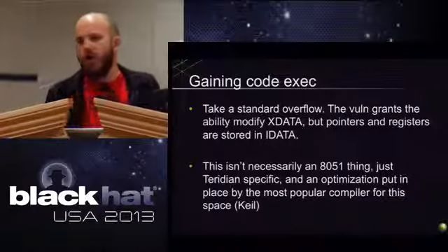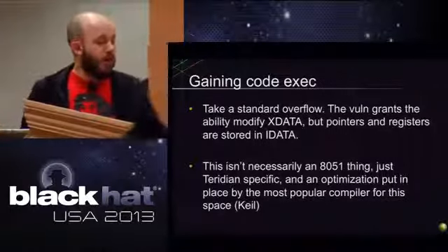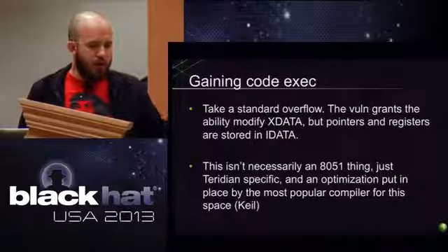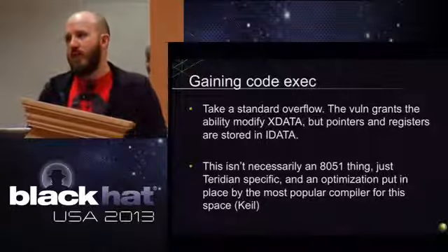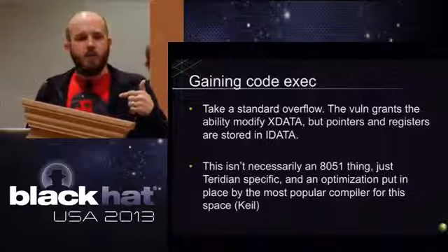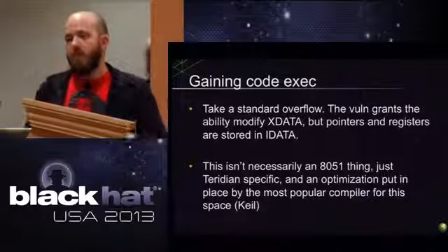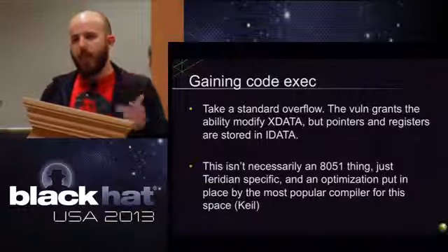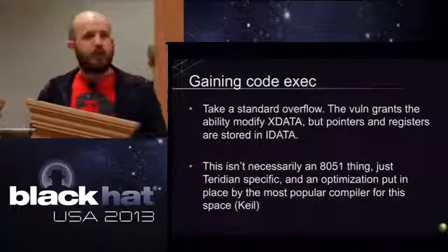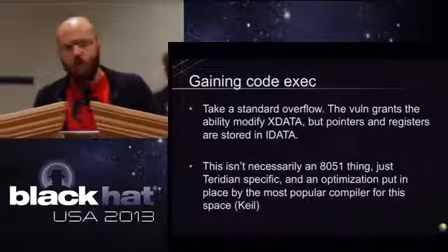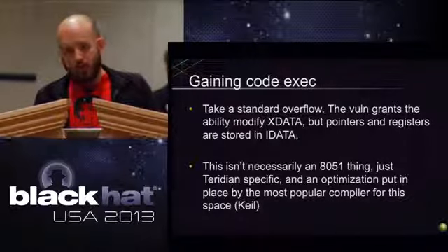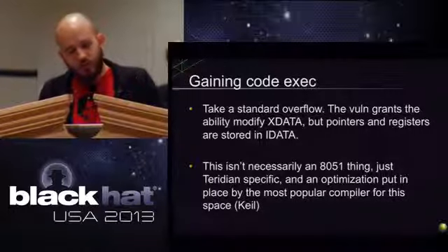There are other, I think Travis's talk that we plugged earlier, he speaks of another 8051 implementation where this is doable because the stack is in a location that is bigger in comparison, and so the compilers for that one don't do this sort of trick where it sticks the stack over here and sticks the data over here. So in those cases, standard buffer overflows would work just fine, but they won't in ours, unfortunately.